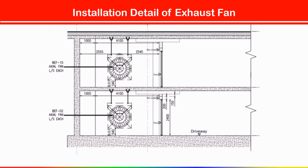Now here one more image is there. This is the front view of the exhaust fan. See how it looks. All details are given. See, from the wall to this fan, how much distance we have to maintain, and at what height we have to install this fan from the finished floor level: 440 mm. Then see, the hanger detail is also given.